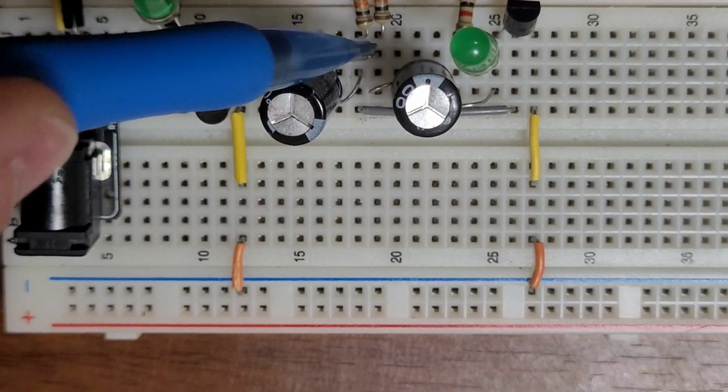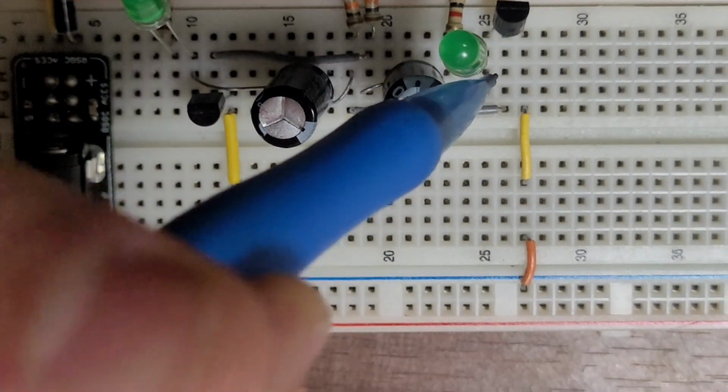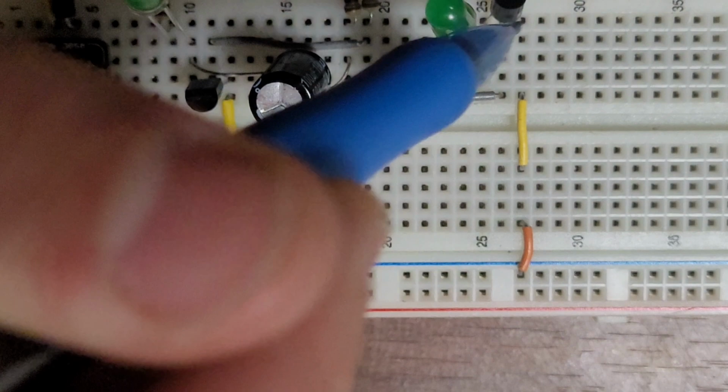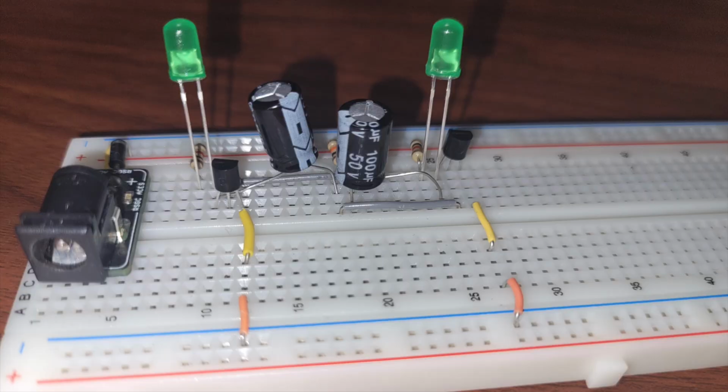A wire connects the base of the NPN closest to the power jack to the capacitor furthest from the power jack into the collector, from where electricity streams out of the emitter and returns to ground. This procedure is mirrored for the other half of the circuit.